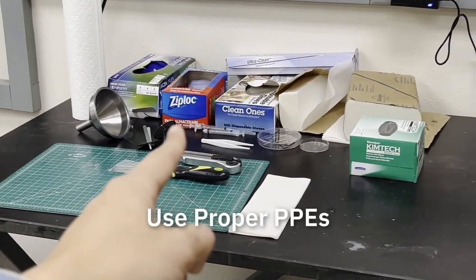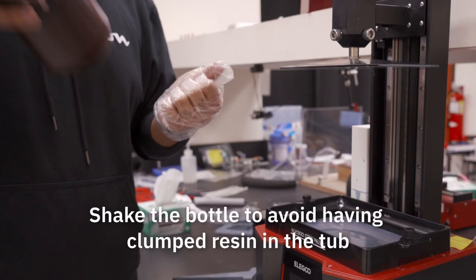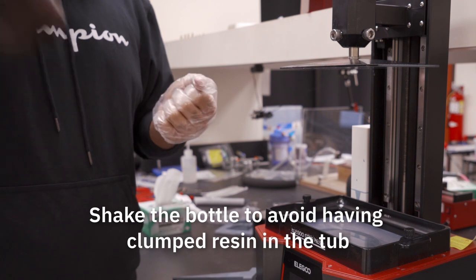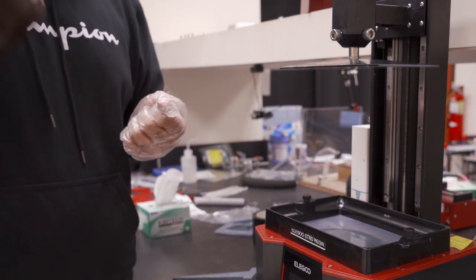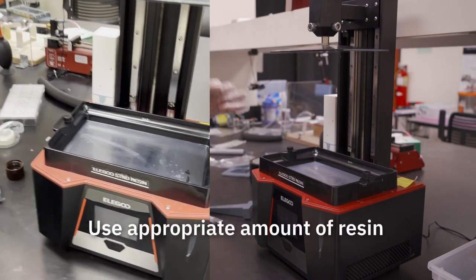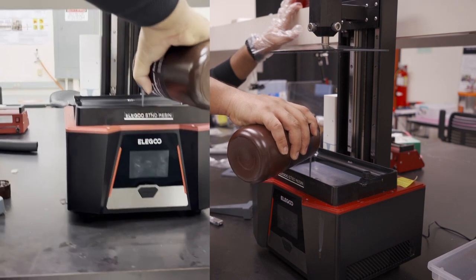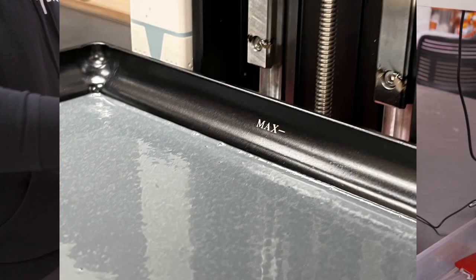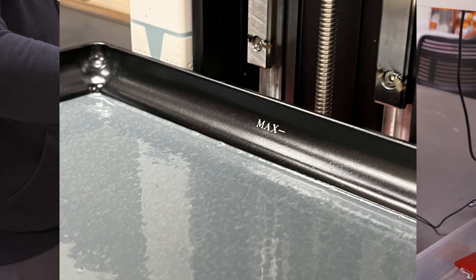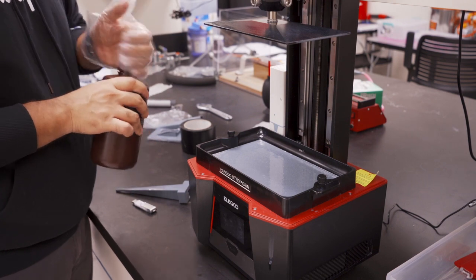Make sure to use appropriate equipment such as nitrile gloves and lint-free wipes. For this tutorial, we are using 8K resin specifically produced for the printer. Make sure to shake the resin bottle to avoid having clumped resin in the tank. Before pouring in the resin, make sure the resin tank and the FPA film surface is clear of any contaminant. The amount of resin that can be poured into the tank is indicated by the max line. For smaller parts, use accordingly smaller amount of resin.